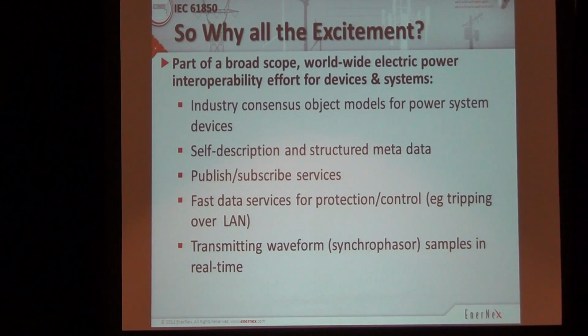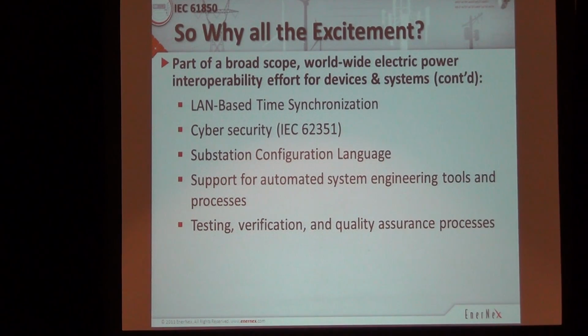We have what we call fast data services. So we're going to call it GOOSE, Generic Object-Oriented Substation Event, but it's basically a very fast communication method that allows relays to share data between themselves very, very quickly and very reliably. And then transmitting data, we call that sample measured values, and synchrophasor is one of the newest and most significant users of that kind of technology. Time sync, you've heard of 1588 and C37.238, which is the power profile for that. Cybersecurity, Substation Configuration Language, which is an XML-based tool that allows machine-to-machine sharing of configuration data. Very, very important, and it supports auto configuration in the future. And then these technologies support this kind of automated tool set that we're talking about,